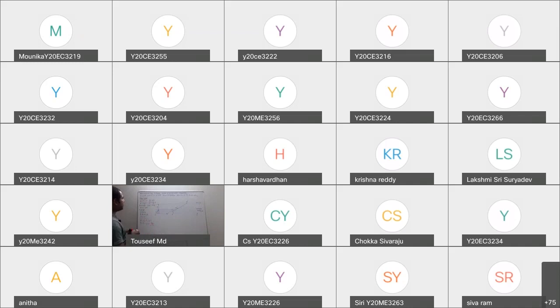So this is the thing we know. And next we know that phi is equal to 50 degrees, so we have only the top view point, which is V, here. So I just take V as center and draw a line of 40 degrees. Now, taking B dash, draw the vertical projector to B. I don't know where on this line of B dash I am supposed to obtain my B. But I know only that VT B dash is going to be the front view.